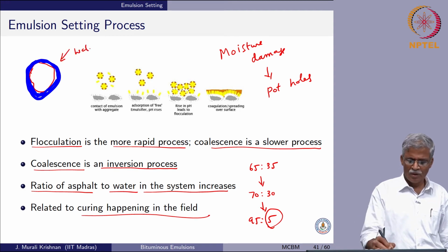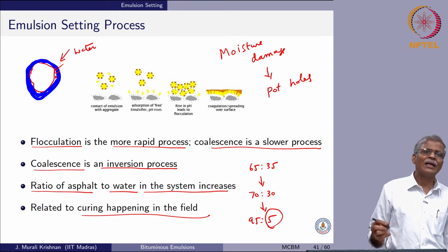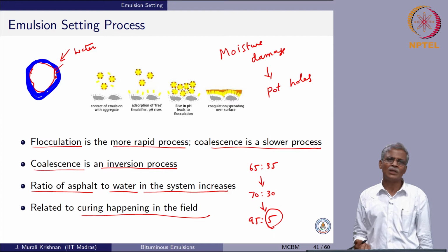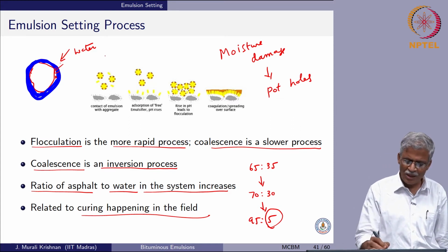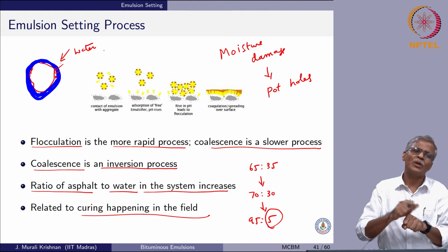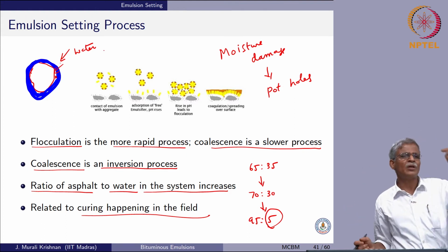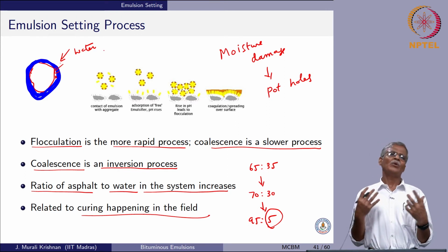What does the water do? It penetrates through, breaks this film, because the aggregate has more affinity to water than to the binder, and that is why you see exposed surfaces, the film is peeled off, and then slowly one after the other the stones start coming out, and you have your pothole.